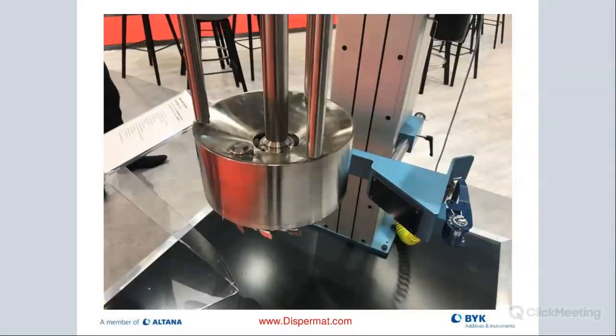Also, even though there is a nano kit available, you're going to have somewhat of a limitation in terms of particle size. On a basket mill, we can go down to roughly 500 to 600 nanometers. If we want to go smaller, then we really need to look at a horizontal mill for really, really small particles.